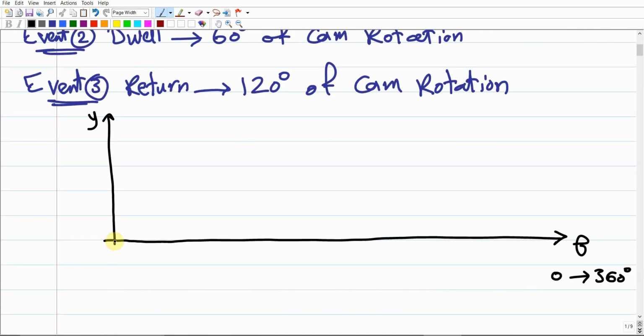So you're going to measure 6 centimeters from the 0 point. Let's say it became here. This length should be the 6 centimeters. And we're going to call this period beta. Beta stands for the rise period. This is the angle of rotation, or the period of rotation, of the cam that is needed to give rise to the follower. So this is beta rise, or just beta.